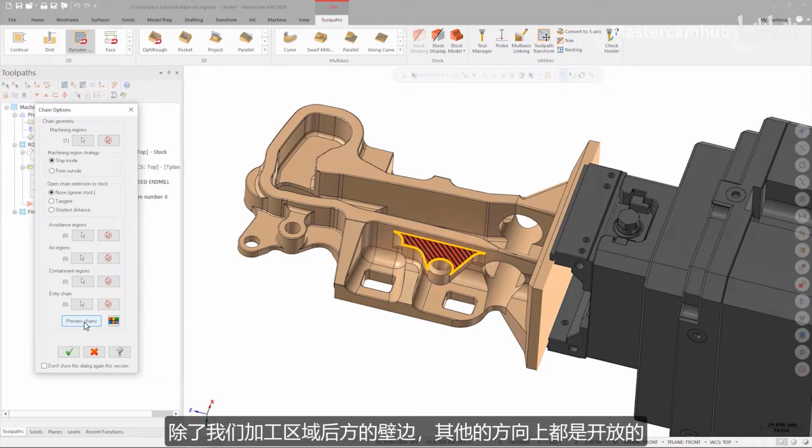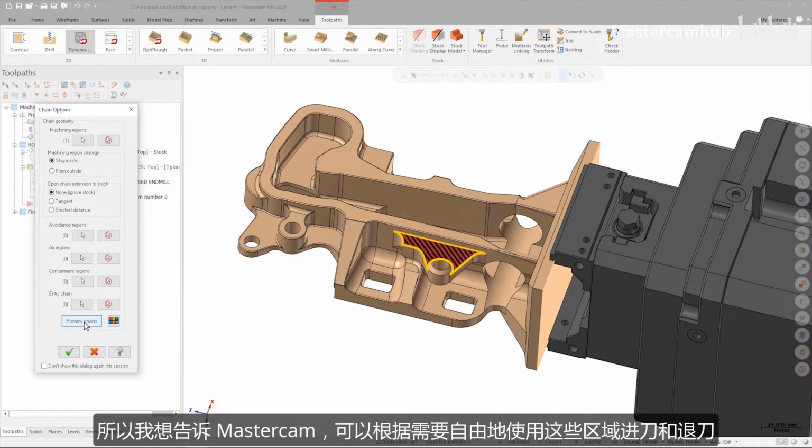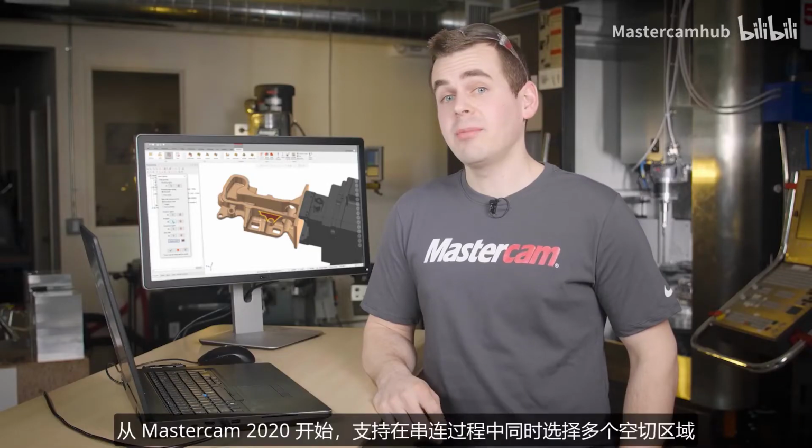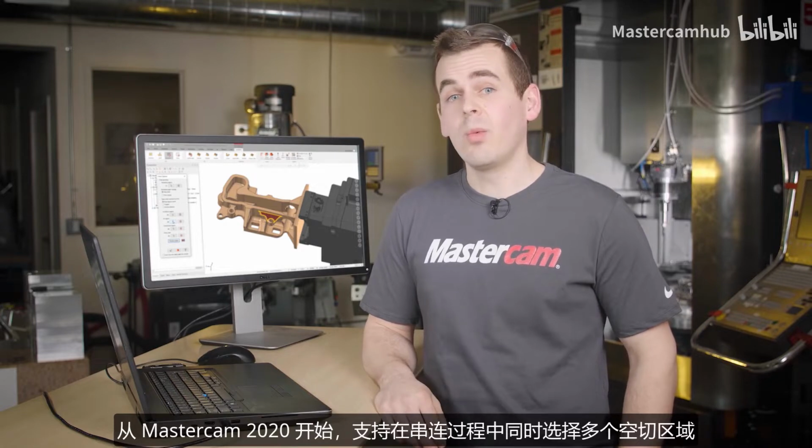Other than the one wall next to our machining region, the other sides of our chain are open, so I want to tell the toolpath that it's free to use some of the space to enter and exit the material as needed. To do this, I'm going to specify air regions. Starting in Mastercam 2020, we now have the option to select multiple air regions when chaining, and the feature on this part is a great candidate for this.